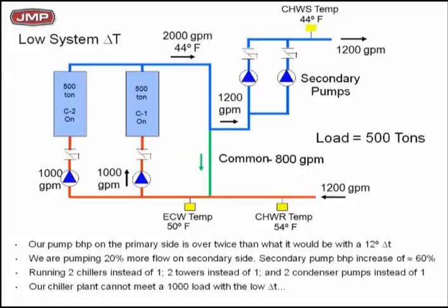So our chiller plant cannot give you 1,000 tons at low delta T. Remember that. If I only got 417 out of it, if I double that, I can only get about 835 out of it. In other words, I'll never get 1,000 tons out of this 1,000-ton chiller plant until you give me hot return water, till you give me my 56. If you're going to insist on giving me 54, I cannot give you 1,000 tons. That's what you've got to understand.